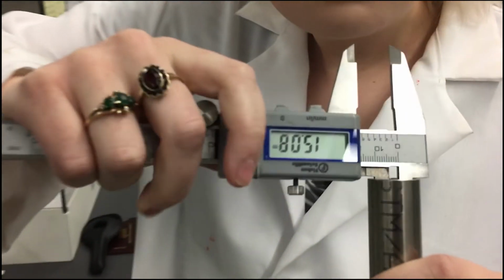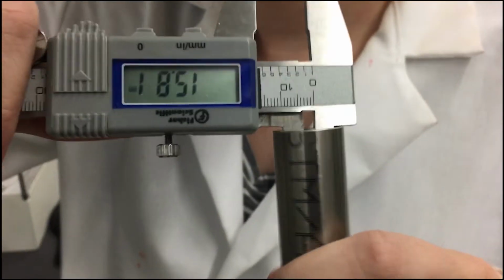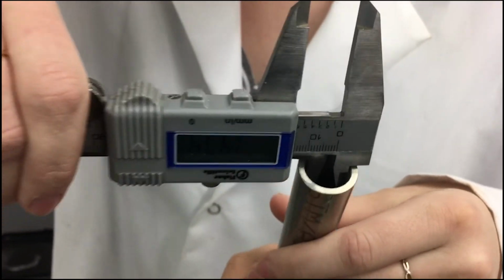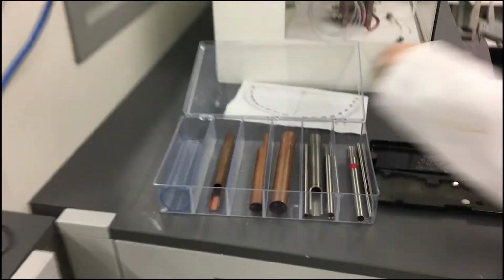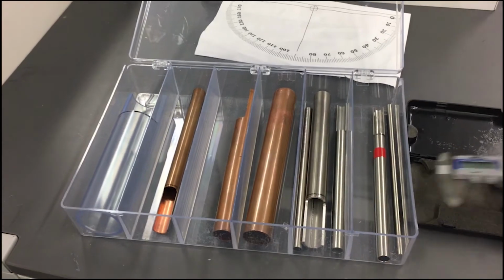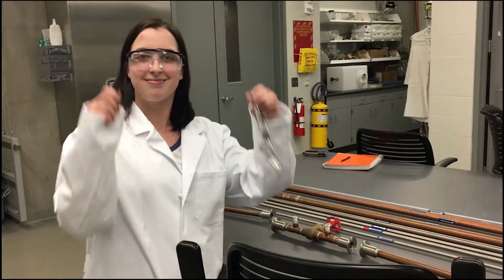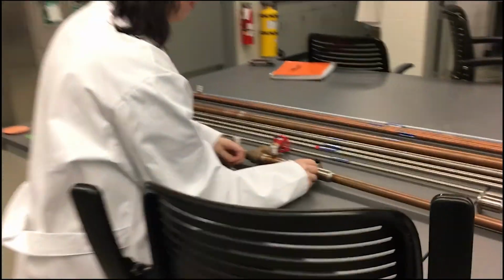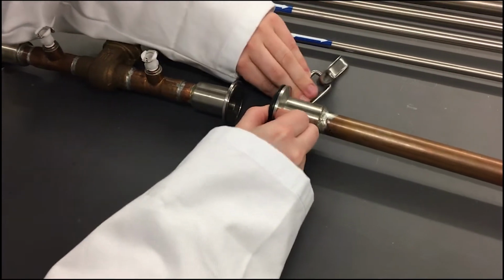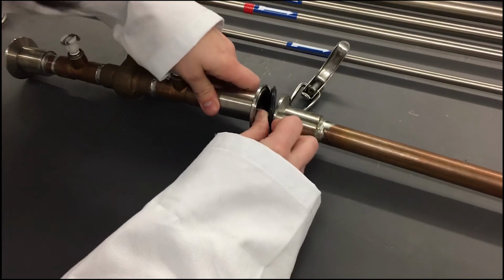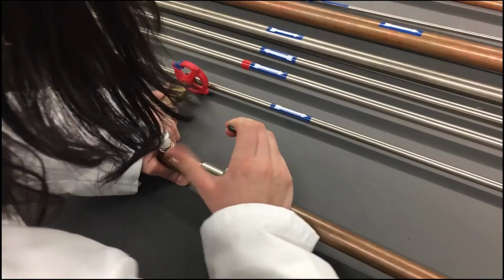Additional data that is important to record in this lab is the length, diameter, and roughness of the pipes, along with the opening sizes of the valve. When it's time to test a valve on the pipe, the valve will need to be attached. The valve should also include 2 rubber gaskets and 2 metal latches. The rubber gaskets are placed between the pipe and the valve to create a seal, and the latches hold the pieces together.